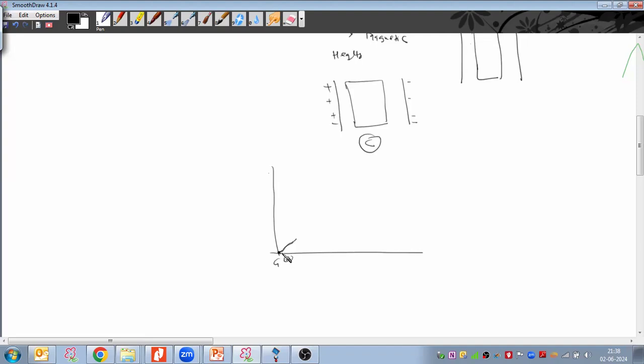And when I move away from the grounded point of the sheath along the length of the cable, the induced voltage on the cable sheath keeps increasing linearly, proportionally, right?